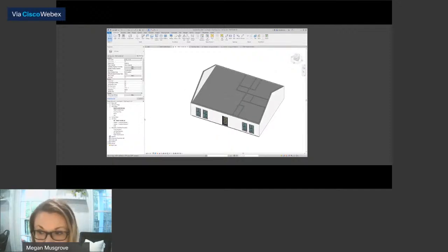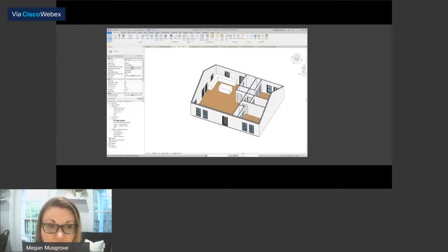One thing that I'm going to do is I'm going to go over here. We've got this first floor 3D. We're going to duplicate that. So right click, duplicate, because I want to do one that has ceilings and one that doesn't have ceilings. I think I mentioned that last week. So we're going to slow click and we'll just make this second one with ceilings. So we're going to go over here to this other one and we're going to hide the ceiling. So I'm going to hover over that and right click it and just hide it in the view.